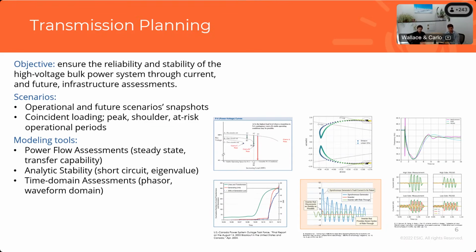And then down at the bottom, we're in the waveform domain. We're actually looking at the fault response on just, it looks like a 4 cycle fault of our system where we're comparing measurement and PSCAD data. So those are the sorts of modeling tools that we're using to do these assessments.